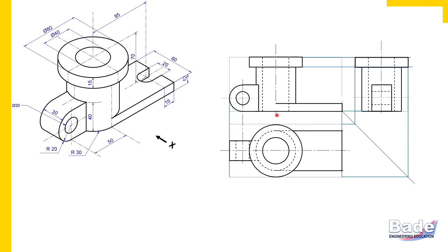And there is one notation used in engineering drawing to indicate a tangential joint on a curved surface, and we are using that notation. Watch here. This small curve at the end of the surface suggests that this strip-like surface merges into the cylindrical surface tangentially. So this is how the top view and front view of the plate is complete.